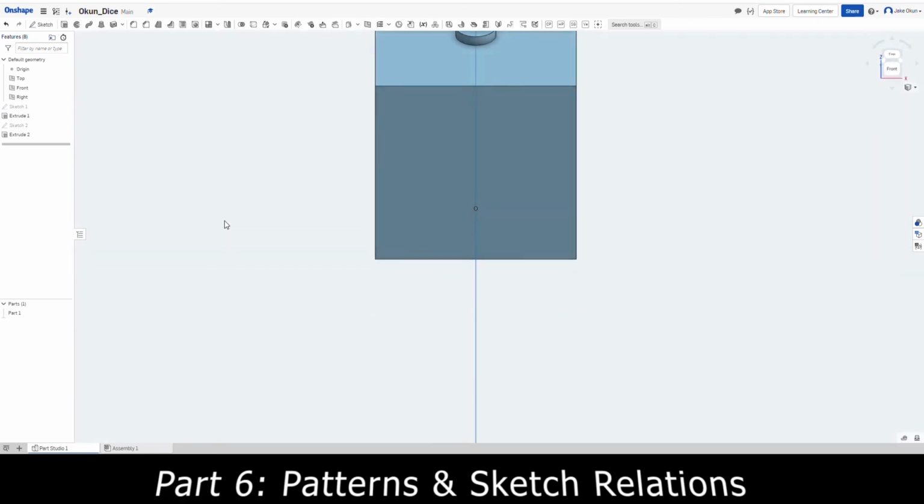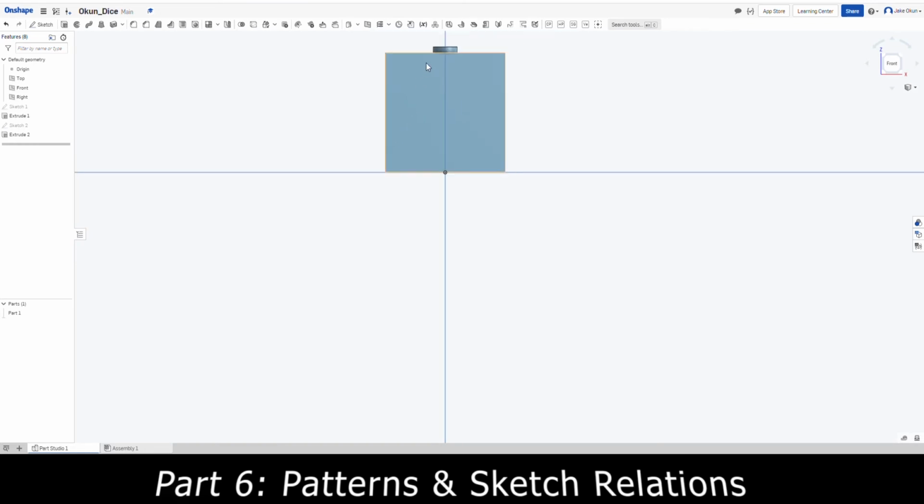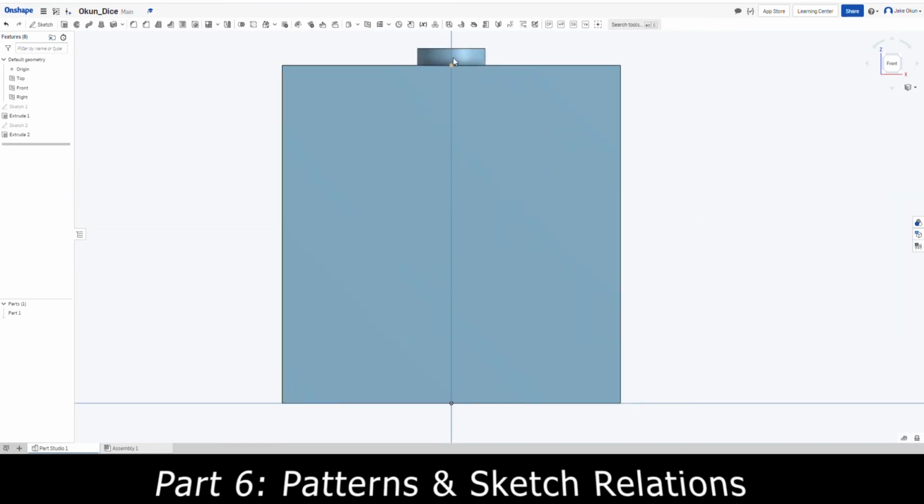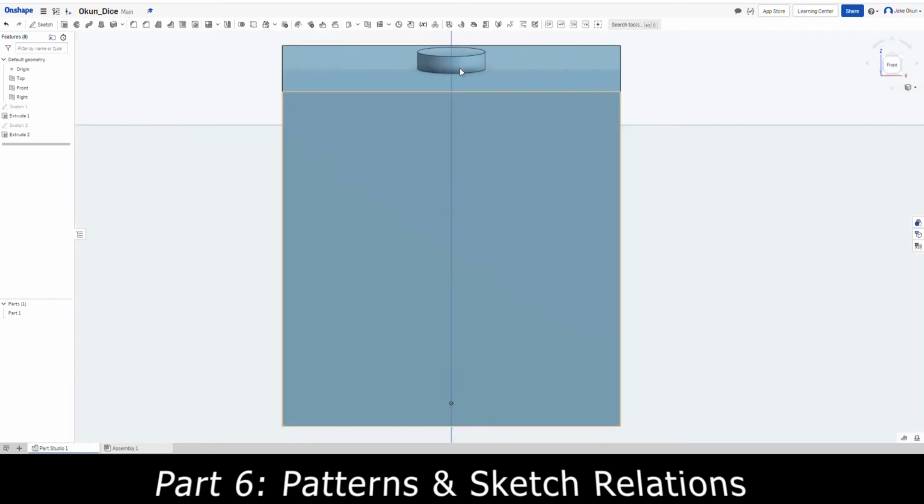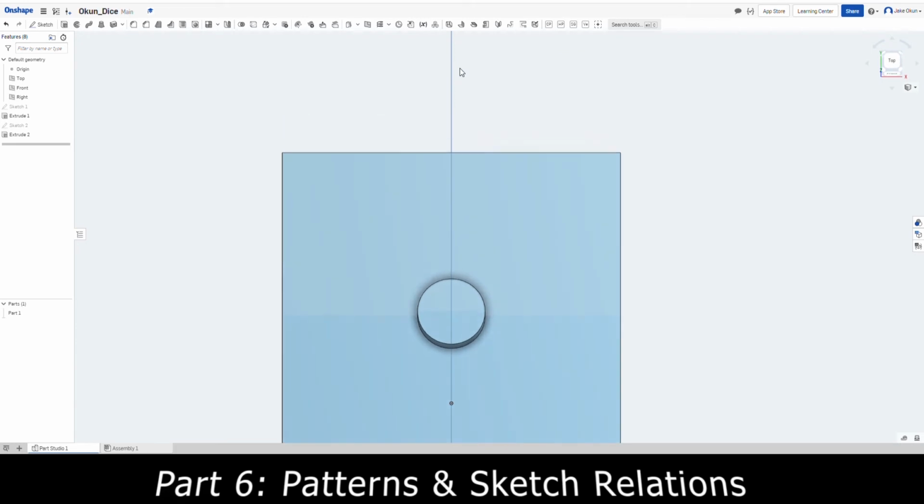But what do you notice here? Is that cut out or is that an extension? That's an extension, right? So you'll see that we don't want that. We want it to be cut out so it's like a normal dice so you can roll it. Just to show you how to do it, I'm going to press the space bar to deselect. Then I'm just going to press Control Z to undo what we just did. This way it'll go right back to what we had before.